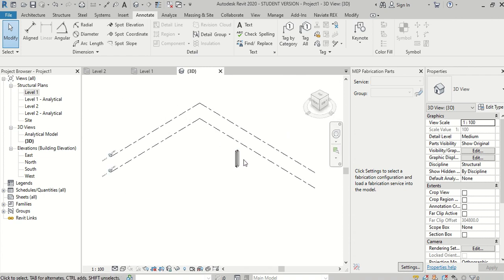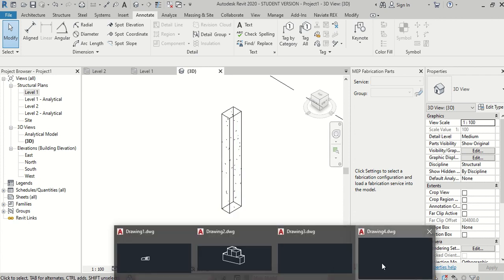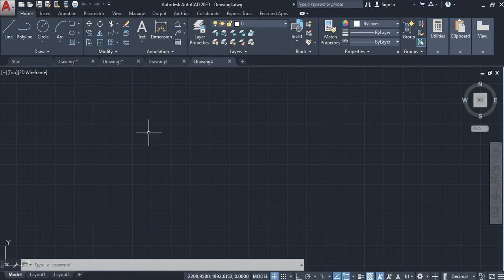So you should understand this idea. So let's apply this idea on AutoCAD. We want to draw the top view of this column, the front view and the side view of this column. So let's start. First, we want the top view, 30 by 45 centimeters or 300 by 450 millimeters. So let's say we will draw in millimeters.